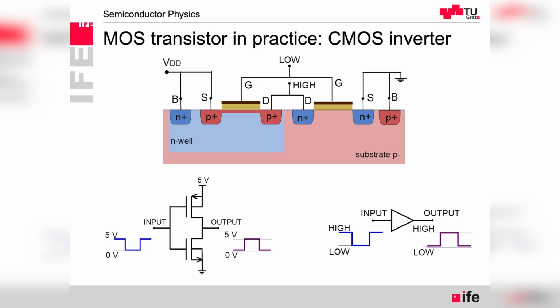Before the ring oscillator, we had the first type of memory cell, which is the SRAM, the 6 transistor structure. Another type of memory is the DRAM, where we have a capacitor and the access gate. Either we switch on the transistor to write the value into the capacitor, or we close it and keep the value stored in the capacitor.